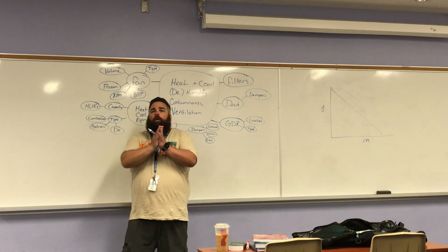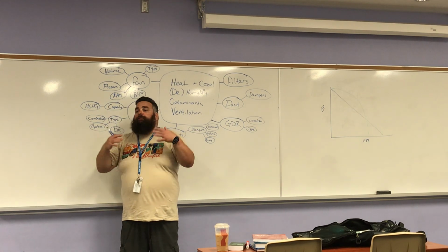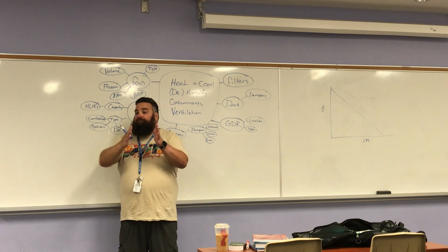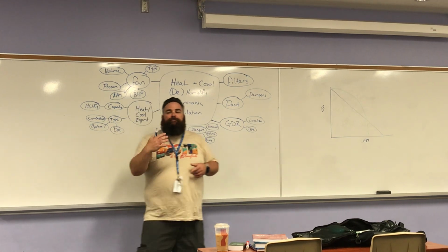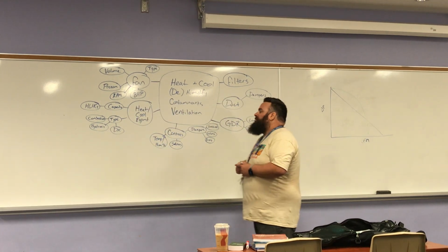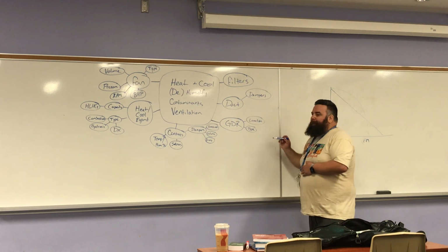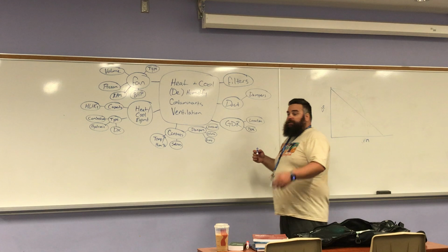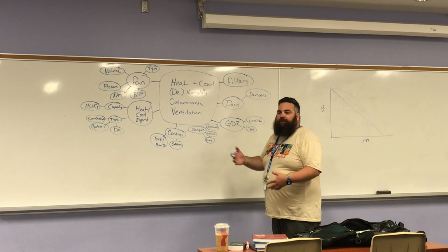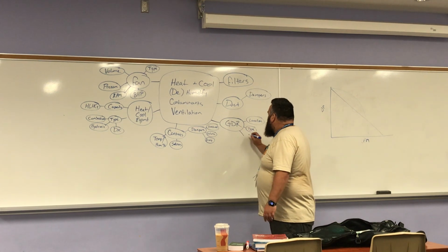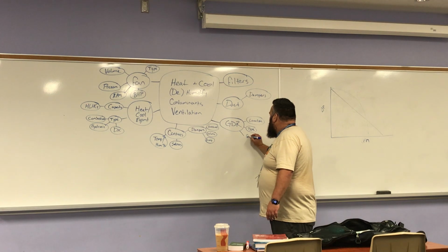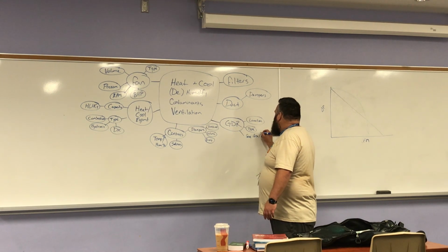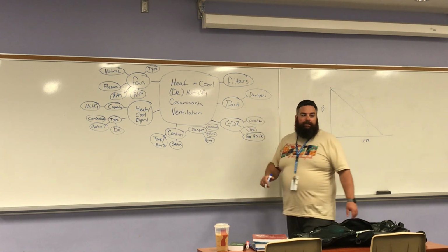So the whole area of that is not free for air to pass through because we have metal in there. So the free area, or the K factor, is what the air sees, and that relates to the size. Different types will have different K factors or different free area. So I'm going to put free area / K. What else?